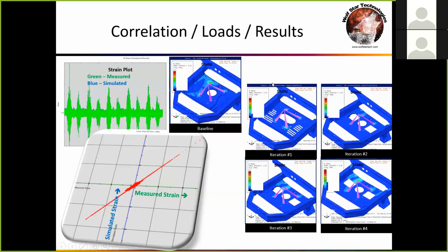And I said, perfect, give me that FEA model. And then we took the loads from the baseline that we've got here, and we took those same loads and ran them into their structure, and you can see that the stress and strain responses are a lot higher. And then working with the design engineer there, inside of a week, we went through 5 design iterations, giving them the airflow that they need and the durability they need for the structure.